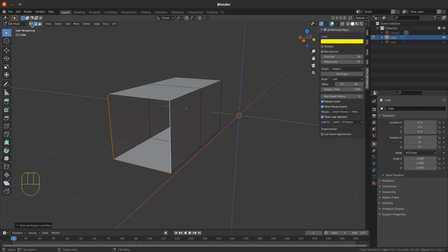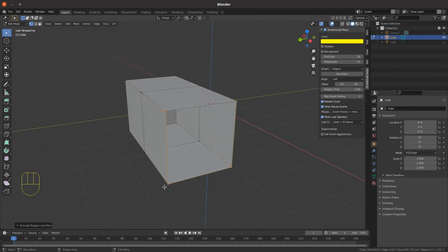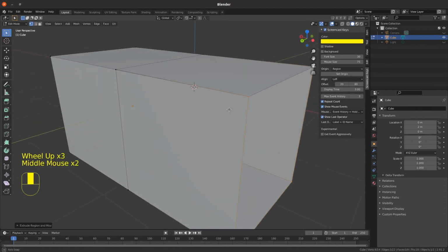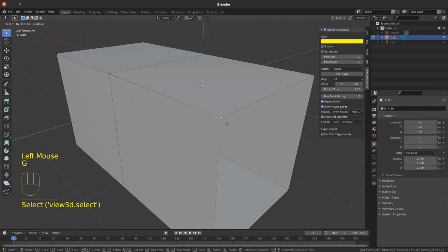if we go back into vertex mode, you can see that we've got the 4 vertices selected, but that edge isn't, and that's an indicator, when you don't have all the edges radiating from a selected vertex, that you've got 2 vertices in exactly the same place in 3D space. So if I just select that and grab, you can see there's another one sitting underneath it in exactly the same place.